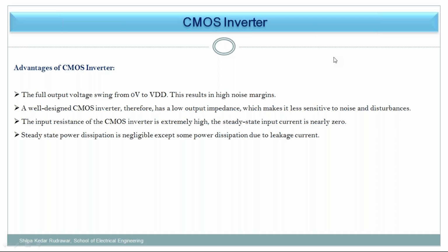Okay, and in that particular saturation region, your MOSFET is acting as a... Can you put your comment in the chat box? In the saturation region, the MOSFET is acting as a constant voltage source, constant current source, that way I am asking. Yes, Yogesh, you have given the right answer. Umesh also gave the right answer. So it is acting as a constant current source. Yes, many of the students are answering. Why? Because the current is constant, whatever the increase in VDS. Okay, hope you are recalling the things. Yes, thank you for your reply.